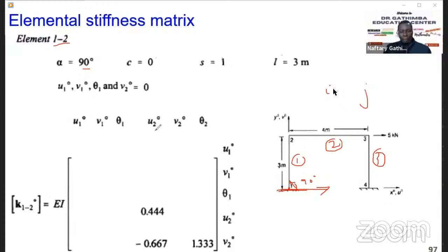For clarity of working, because our matrix is going to be bigger. So to reduce the working, because we knew one thing: when you come to the solution, we develop what you call the reduced stiffness matrix. The reduced, not stiffness matrix, the reduced finite element equation. And we reduce it by removing the rows and the columns associated with the degrees of freedom which are equal to 0.